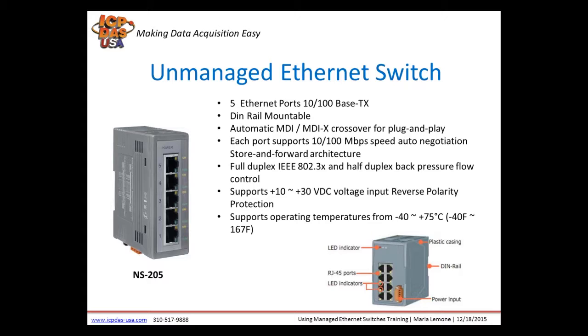There are activity linked data rate LEDs for each port, which aid in troubleshooting. This is typical of most Ethernet switches. Port connectors are shielded RJ45, and it contains a soft start function with overload protection and high voltage protection. They operate in a wide range of operating temperatures from -40 degrees Fahrenheit to 167.